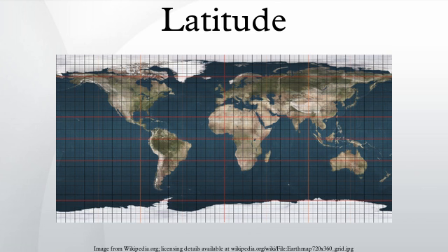Isometric latitude. The isometric latitude is conventionally denoted by ψ. It is used in the development of the ellipsoidal versions of the normal Mercator projection and the transverse Mercator projection. The name isometric arises from the fact that at any point on the ellipsoid equal increments of ψ and longitude λ give rise to equal distance displacements along the meridians and parallels respectively. The graticule defined by the lines of constant ψ and constant λ divides the surface of the ellipsoid into a mesh of squares. The isometric latitude is 0 at the equator but rapidly diverges from the geodetic latitude, tending to infinity at the poles. The conventional notation is given in Snyder.